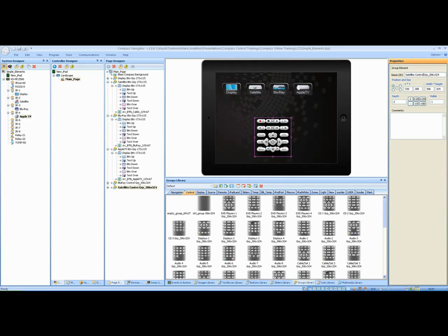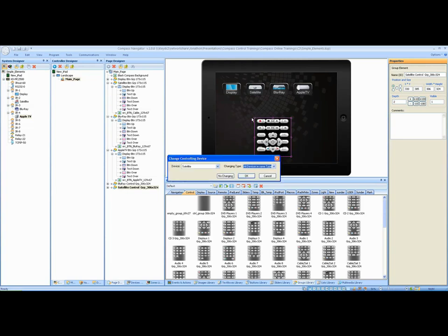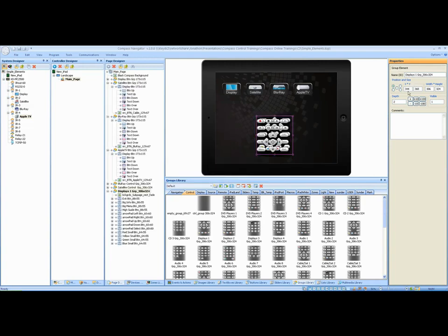And we will now add the, let's see, the display. Okay, so let's take a look for some display buttons. Here is display 1, so let's go ahead and drag that on over. And really these button groups aren't of the utmost importance, so if you don't see one in the display group that you like, for example, to control the display, it really doesn't matter right now. Okay, the X position 330, the Y position 385.